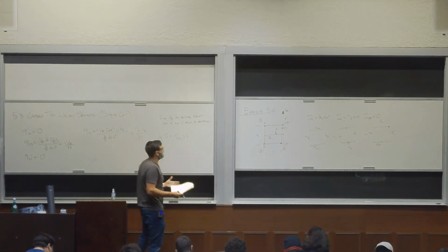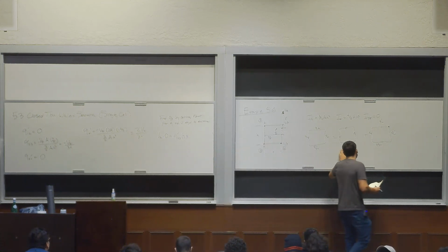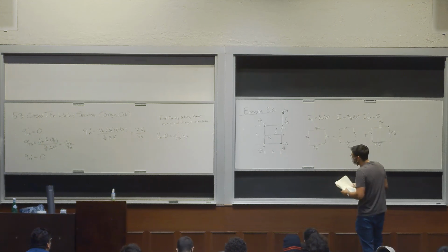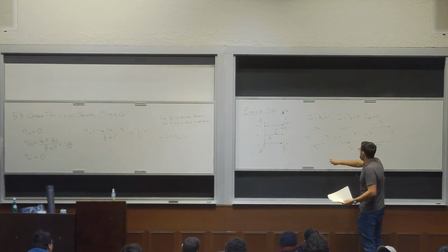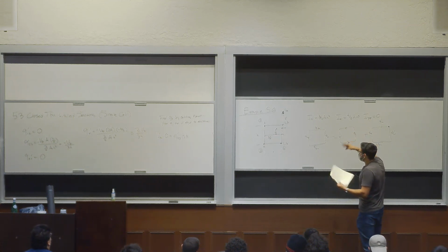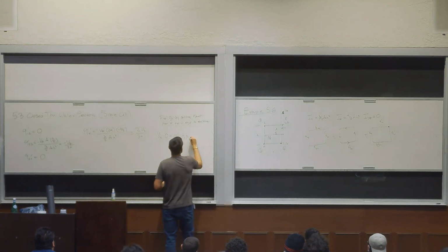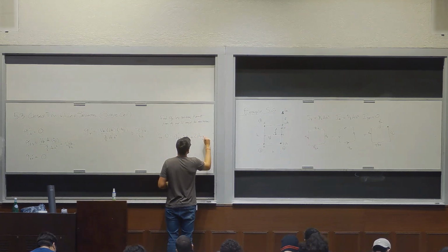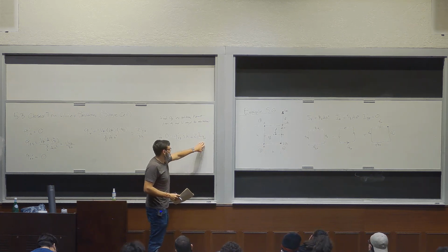And then we also have to add the contribution of Q naught. We're ultimately trying to solve for Q naught. And the torque generated by Q naught doesn't matter what axis you're looking at. The axis could be here, it could be here. The equation for it is the same, always. And the equation is 2A Q naught, the area enclosed by Q naught times that.